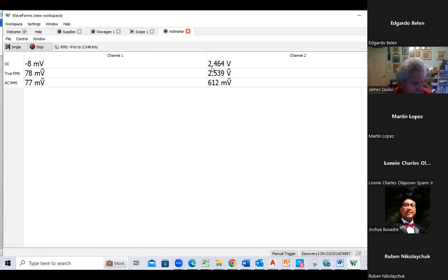That tells me that I wanted my collector current to be 1.26 milliamp. It looks like it's 1.73. Okay, and let's just for kicks see where my base is right now. Let me move that probe, that's the orange one here. If I move it directly onto the base, that says my base is about 1.46. That's a good place for it.